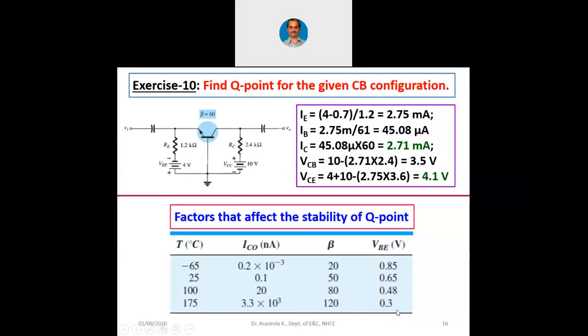That is why we say the transistor or the diode will have a dynamic resistance. Means the resistance of active devices is never a constant thing. It can vary based on the way in which it is biased or based on the way in which the ambient temperature is there.